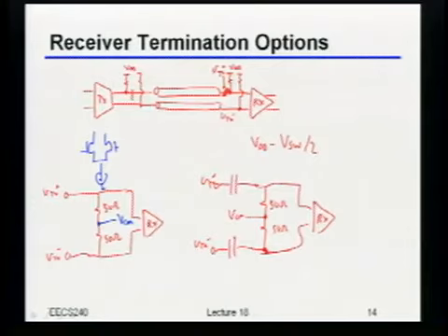Now, obviously, if I do this, I have to be a little bit careful. So what do I have to be careful about? Yeah. The cap must be large. Okay, the cap has to be large. What is the size of this cap going to set in terms of things at a higher level that I care about? The impedance times the frequency at which. Okay, the frequency at which what? Or high pass corner. Yeah, it's the high pass corner, right?